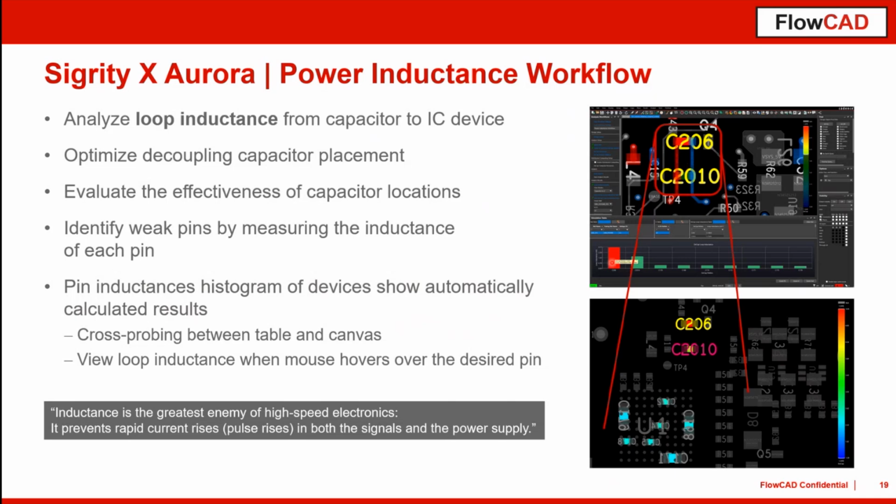So it is now a very nice way to double-click here on such a capacitor. The tool automatically jumps into the design again, shows where the capacitor is located, and then you can see, oh yes, I understand, we have a very long, or not so optimal, connection from my capacitor pins to the power distribution network. Let's move it away, optimize the connection, reduce the trace length, and rerun our simulation. Then you can be sure that you will achieve a better result that even goes in the direction of the rest of these capacitors.